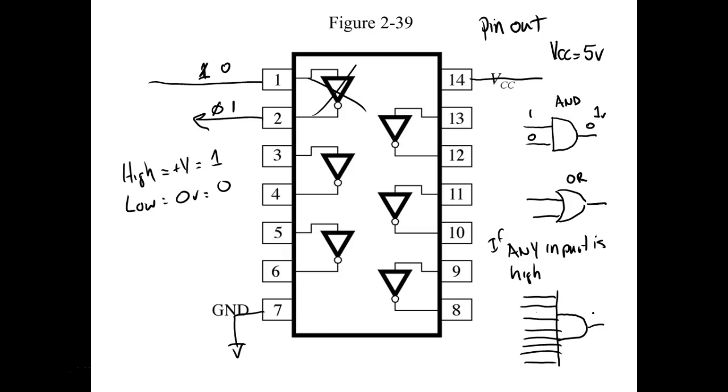But it still is all highs to get a high. So if I came over here and I saw this, the output would be low because that's not all highs to get a high. And that's why learning the expressions is better than learning truth tables. We have a way of reduction called Karnaugh maps, which deals with truth tables.